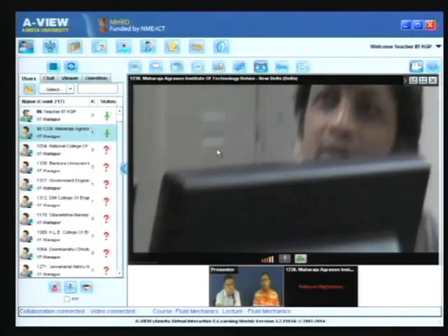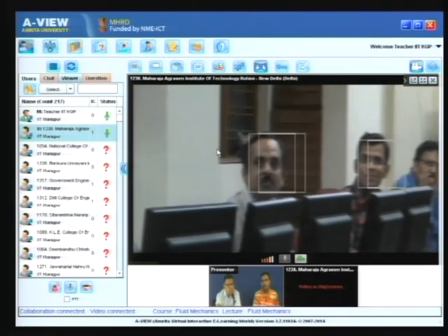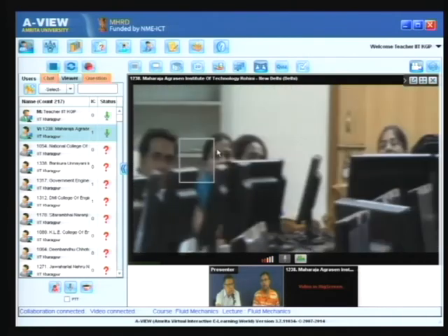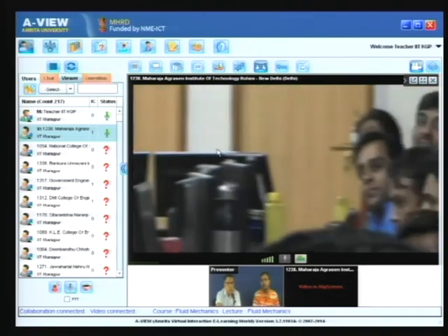Again, this is not a subject of today's discussion, but we can say that your question belongs to a specialized topic altogether known as rheology. In rheology there are devices called rheometers, which can determine the effective viscosities not just for time independent fluids, but also time dependent fluids. The fluids which have apparent viscosity as functions of time have special names, such as thixotropic fluid, rheopectic fluid, and these are very complex fluids.